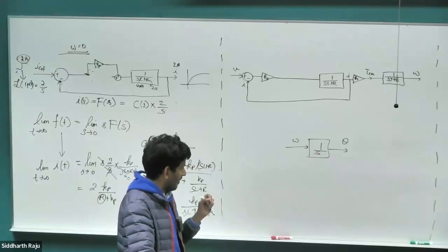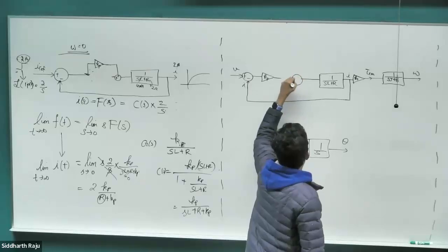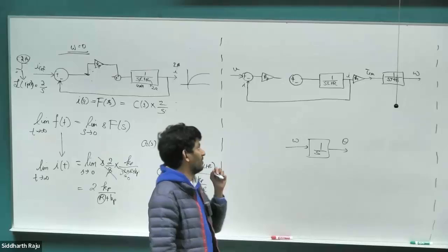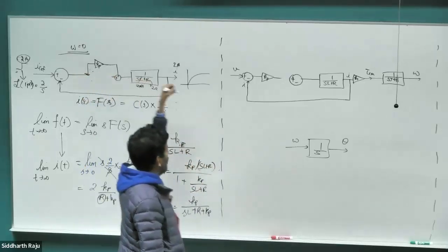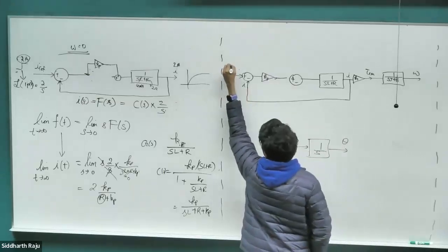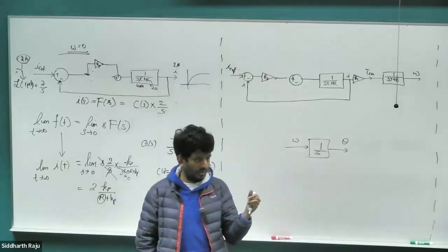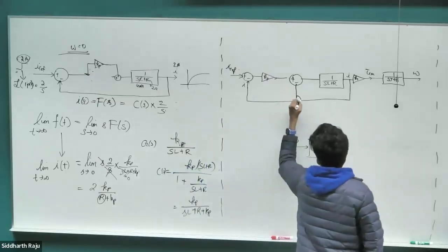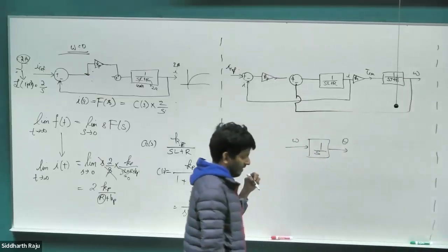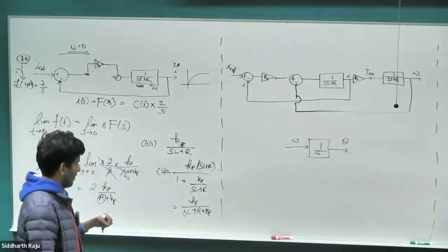It's a little bit more complicated. Jonah already jumped the gun and asked me the question. The term that I had ignored there was the back EMF. I can't ignore the back EMF because I said I'm locking the rotor, but in reality, the rotor is going to be rotating as soon as I apply some reference. This again is IREF. As soon as I apply some current, I've started creating torque in the motor and the motor is going to start to rotate. So there's going to be an EMF term. How do I find the steady state error now? There's still going to be a steady state error.